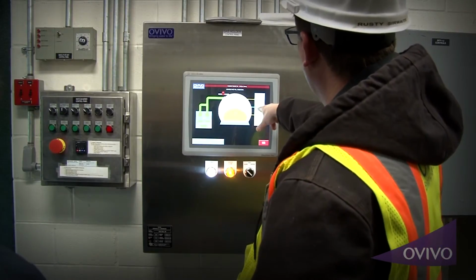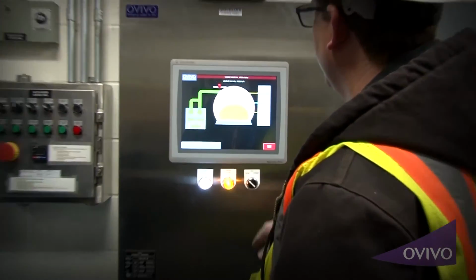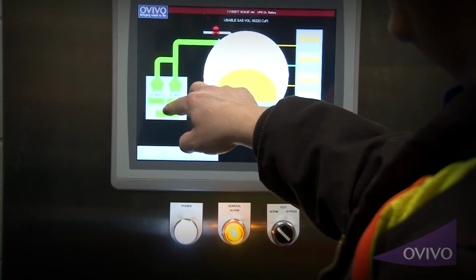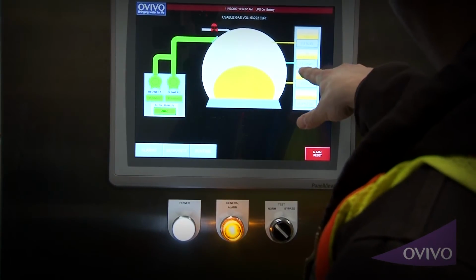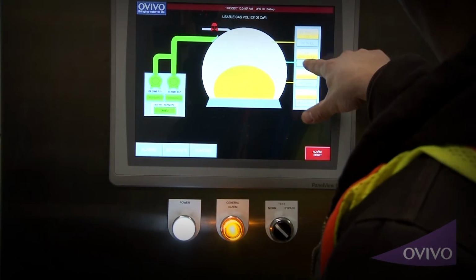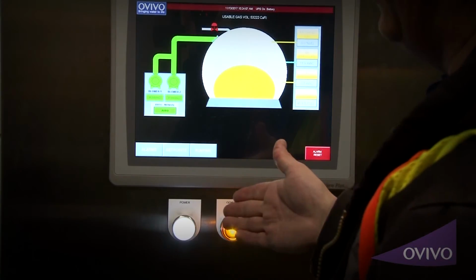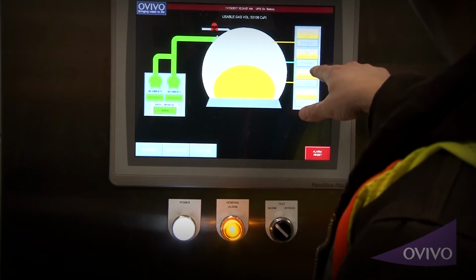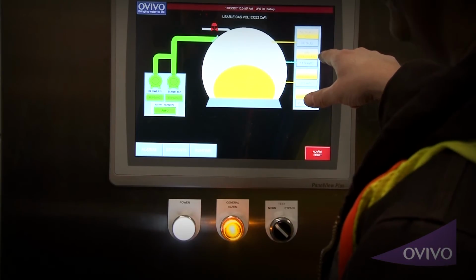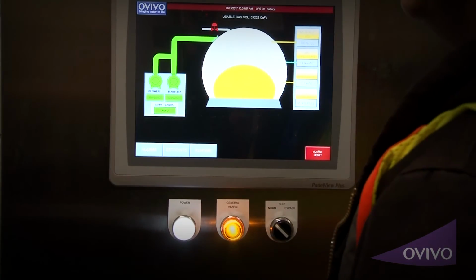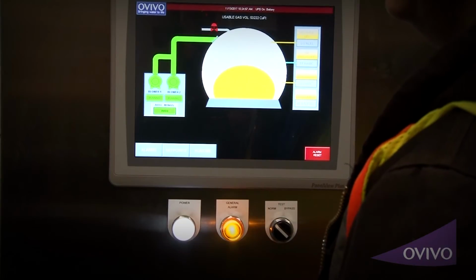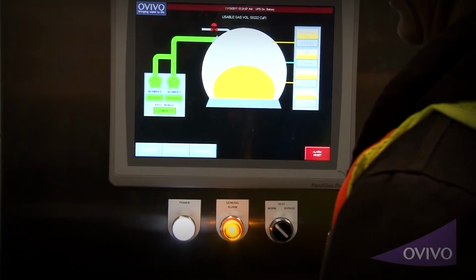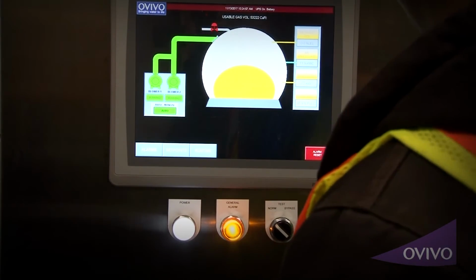Okay, so it's at 11.9. It went down past the 12, and it automatically kicks on both blowers. The second it does that, it'll stay on till probably it hits 12, and then it'll go into standard operation mode, which would just be one fan. Just like if this thing were to ever hit 14, it's set at 13 inches of water column. If it hit 14, both fans would go on until it comes back down into range, and it'll actually do that.